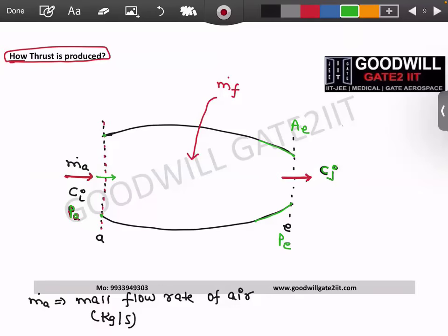You people do that, right? That is what we are trying to develop here. So if you see, your area is reducing, right? Now again, this is not that simple here, because you will be using some convergent divergent nozzles also, but in propulsion we are not going to discuss that. That is part of your gas dynamics syllabus. So as of now, don't worry, you have some exit area which is important for calculating your thrust.